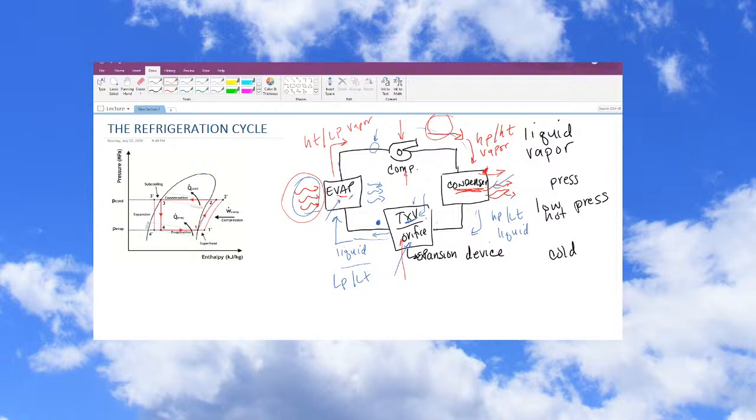Just like your radiator. If you stick your front mount intercooler in front of your condenser, which is in front of your radiator, then you can have issues where you don't have enough cooling to keep the engine cool and all that. Because this gets hot. I mean, it's a source of heat. So now my radiator, instead of seeing atmospheric temperature air, it's seeing 100 something degree air on the front of it. Well, it's not going to pull a lot of heat out of the coolant if I'm feeding a bunch of hot air in front of it.